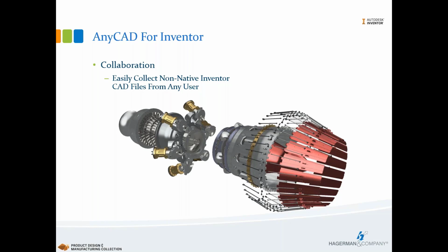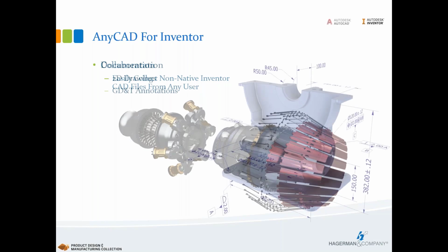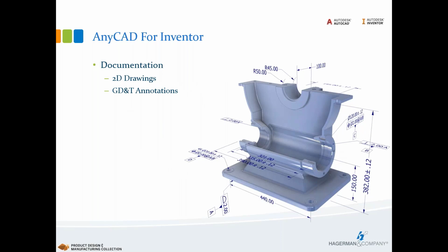Now we can still open them and we can still convert them to Inventor files if we want to make edits to them. We can use our direct edit capabilities, commands inside of Inventor to resize, to shrink, to extend. You know, if we need to work around it for clearance, we can extend the size of one. We can simplify them, make different shapes of them so that we can make sure we can fit this in our factory or our layout where we're working with. But it's just utilizing those tools. And then once we've got the model open, we can utilize it on the 2D side. We can use the 3D modeling annotation tools inside of Inventor that we're working with there.